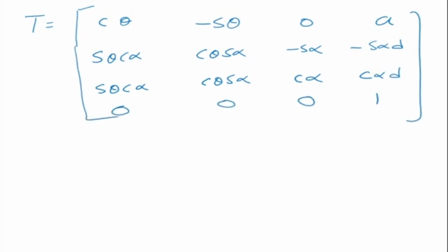Okay, what is the use of this DH parameter table? What is the use of this generalized matrix? In a computer program, we can write the DH parameter table, which is a matrix, and then you take one row of the DH parameter table, put it into this matrix, and you'll get your respective transformation matrices. We'll write a computer program at the end today and see how that can be done.